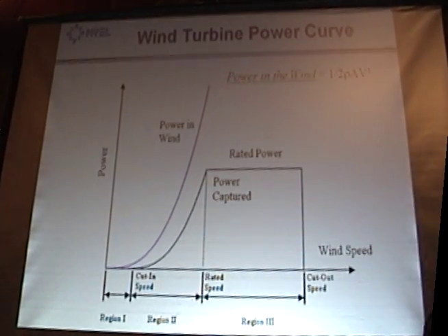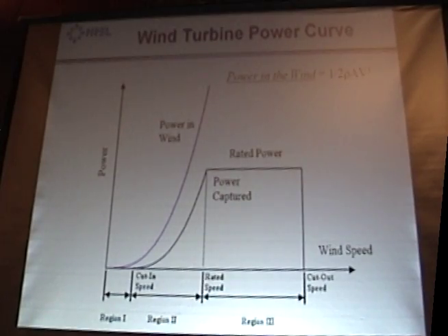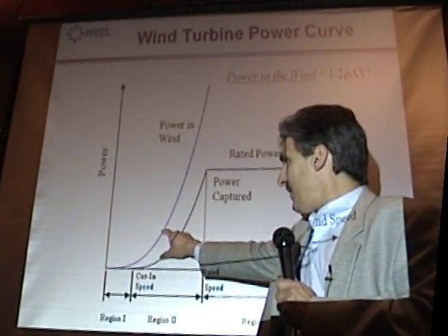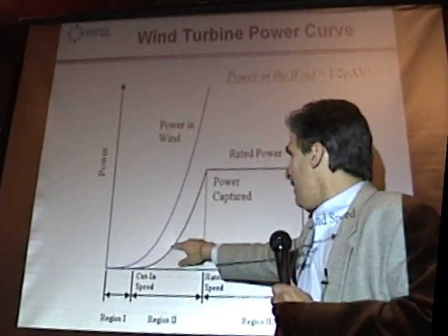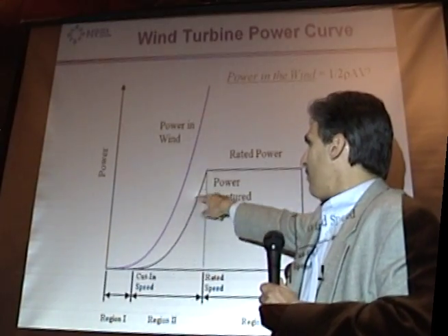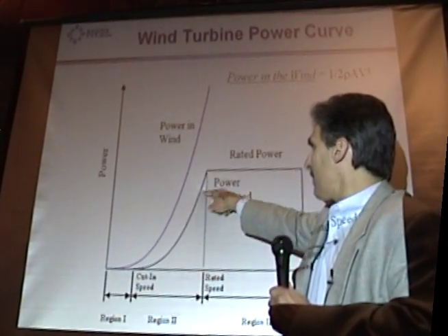A good way to think of that is if you completely stop the wind, then no wind would be passing through the rotor. You'd take all the energy out, but there would be no energy made either, because it's just like a wall that's blocking it. So there has to be some movement of air through the rotor, and 59% is the amount that can be captured.